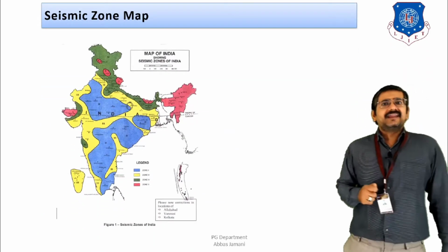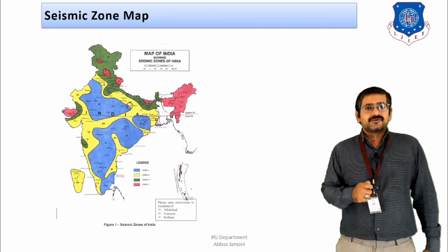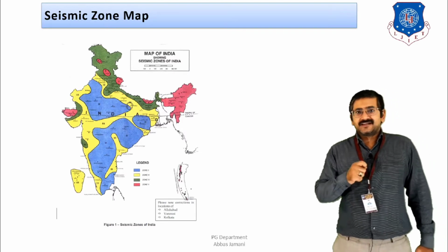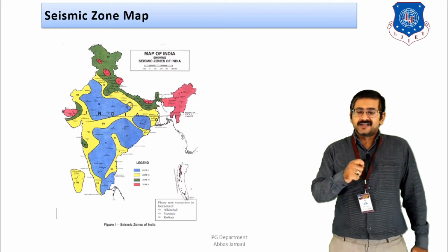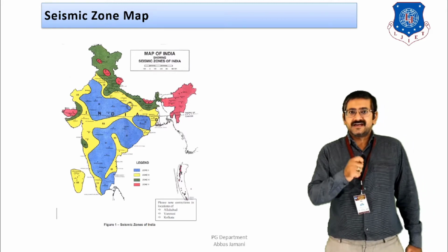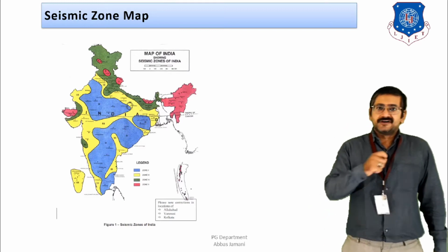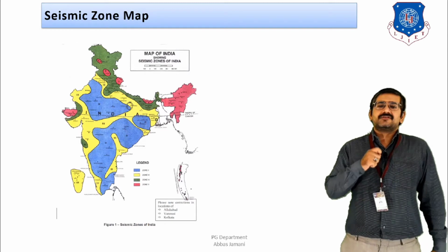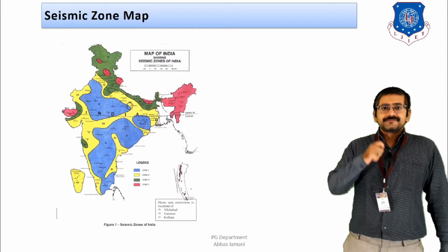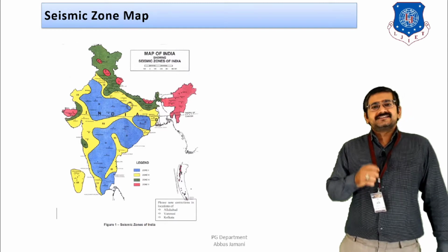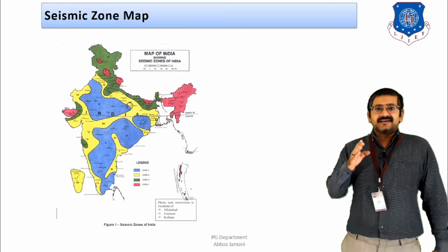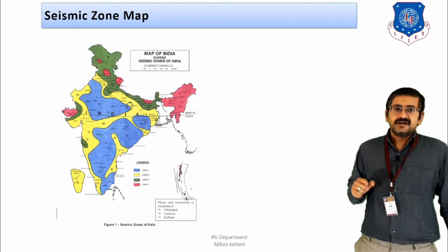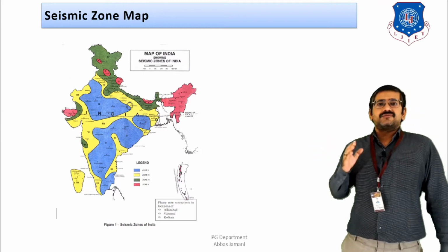So whenever you have any design project, you need to finalize the earthquake parameters based on IS 1893, which you need to introduce in the model that you are going to make, whether it is in STAAD or in ETABS. And the first question is regarding the location of the site where the project is proposed. So the Indian Standard Code initially divided the entire seismic map of India, as you can see over here, into 5 zones, that is zone 1, 2, 3, 4, and 5, right?